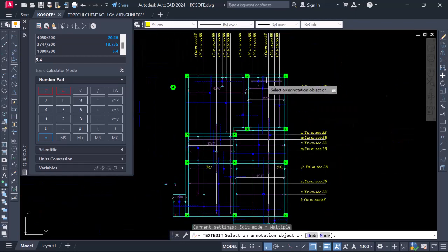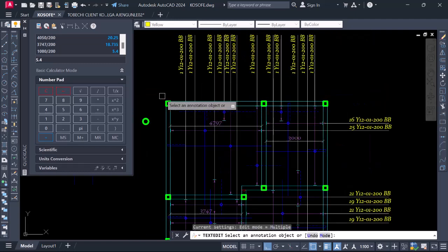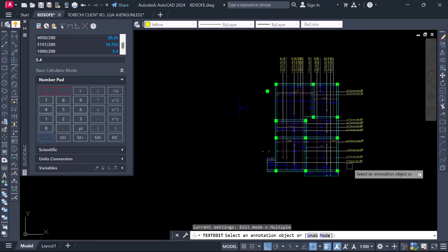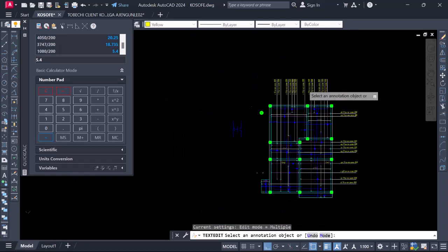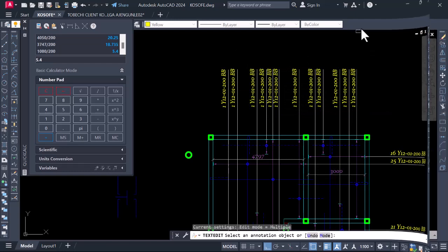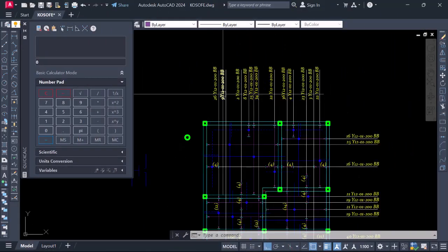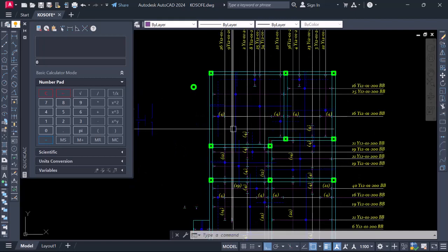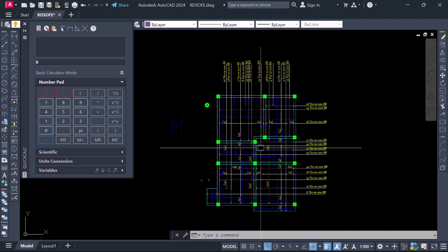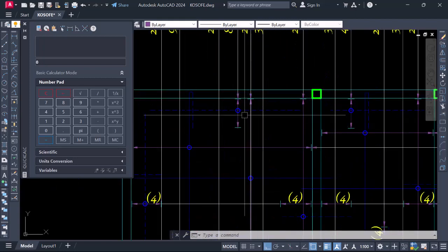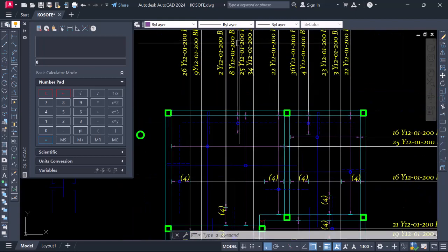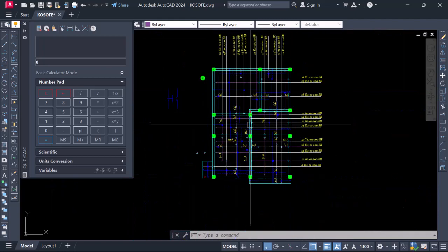So the same thing we'll be doing, by taking the span divided by the spacing, and whatever we have, we're going to add plus 1 to it as a factor of safety to get our number. The same thing we did here is what we'll be doing at this point. So I'll be doing this point and we'll get. So about this time, we have successfully labeled all this. Note, what I did here is the same approach I did in the horizontal direction. You try to get the span and divide it by what? By the spacing, all right? So just want to save time.